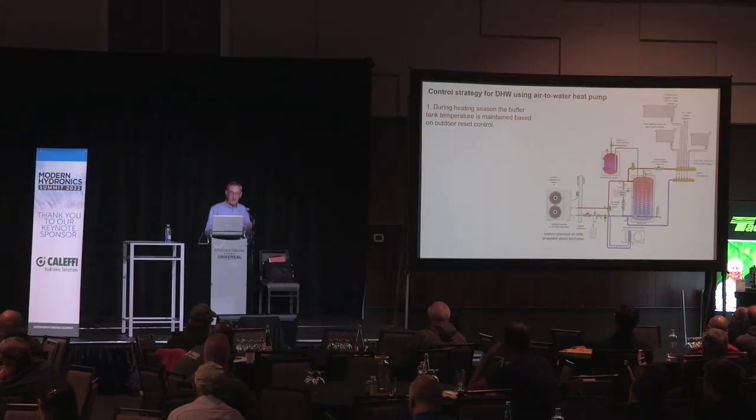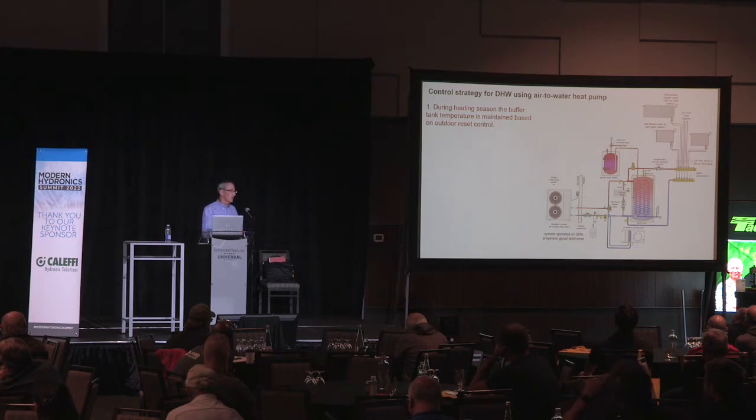So you'll see, I'm just showing a conventional, maybe a 30-gallon electric water heater. There could be other options. It could be a tankless electric water heater. It could be really anything that can give you a boost on the domestic water. I'm also showing in parallel with it an electric boiler. And this is assuming now you want to go to a full electric system, okay?